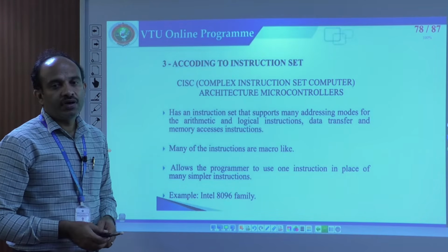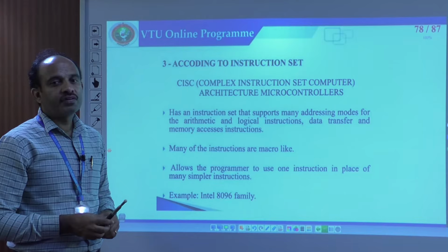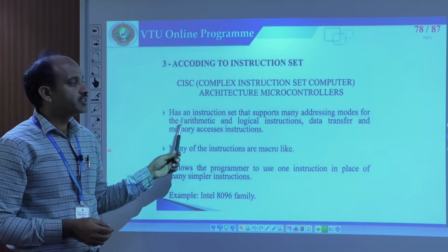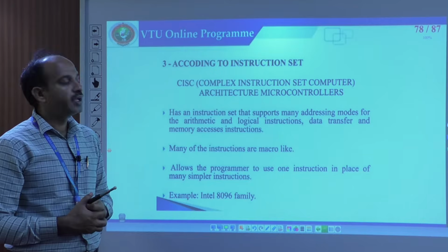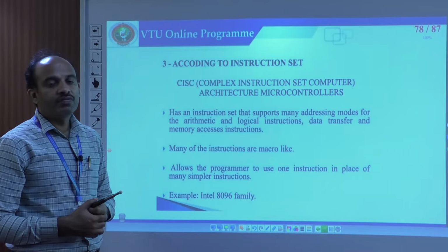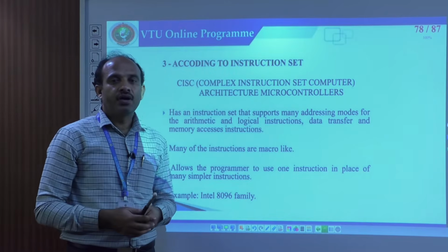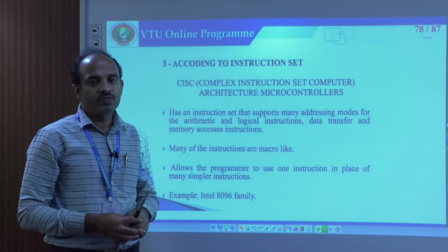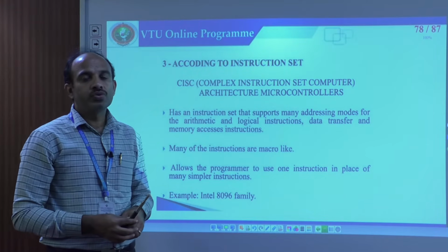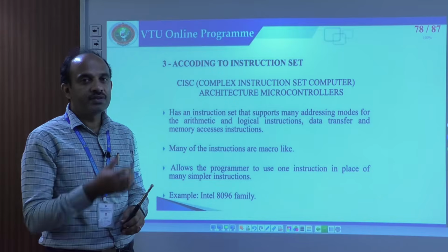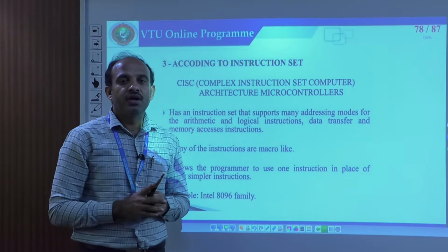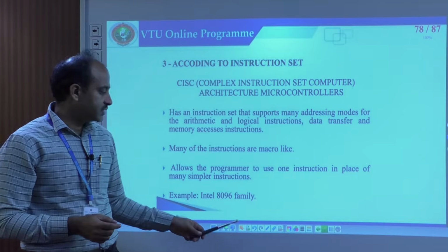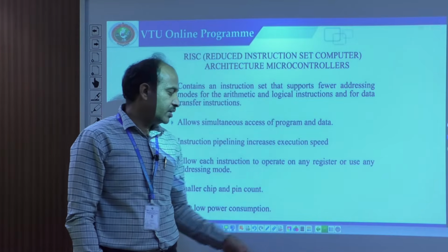Now, instruction set: already we have discussed complex instruction set computer architecture microcontrollers. It has an instruction set that supports many addressing modes for arithmetic and logical instructions, even for data transfer and to access the memory. And many of the instructions are macros, which allow the programmer to use one instruction in place of many simpler instructions. An example of such a CISC is the 8096 of Intel.